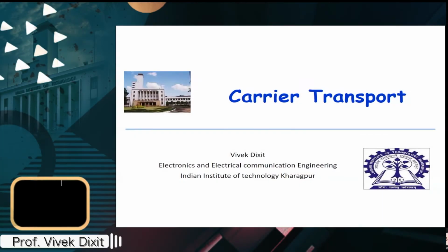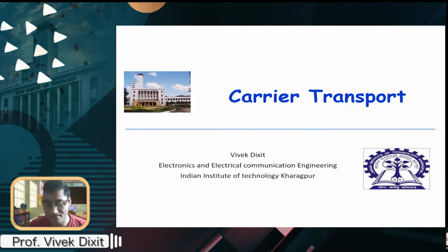The carrier concentration in equilibrium, and then how the carriers are generated. So what are the different mechanisms for generation, such as band-to-band generation through optical photons, or through thermal, or through injection, right? Injection is of course another mechanism, or trap-assisted recombination. Then Auger recombination. So these are the different mechanisms that we have discussed, right? One important aspect is which governs the